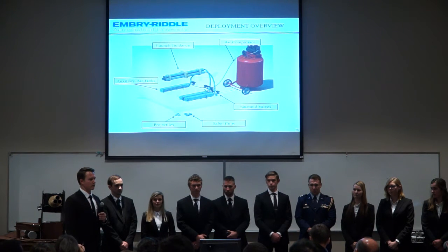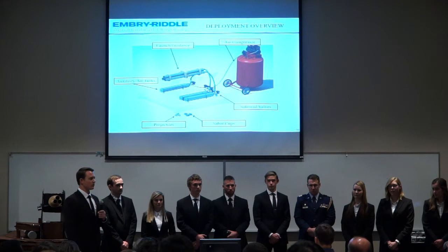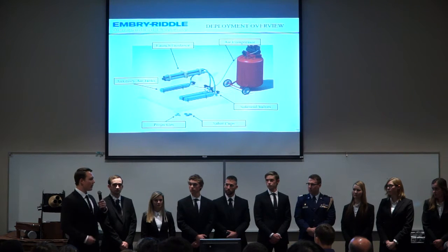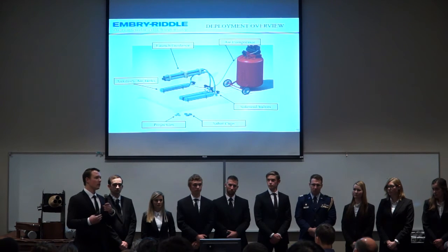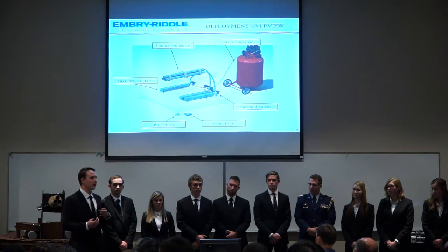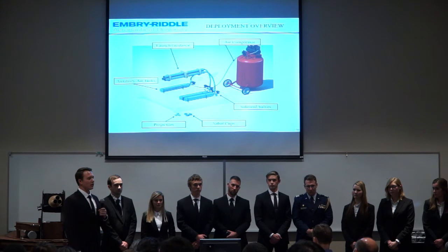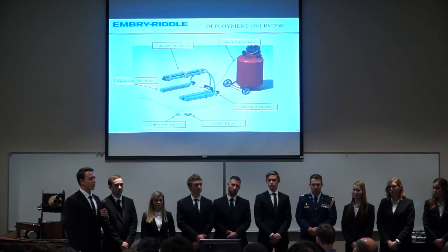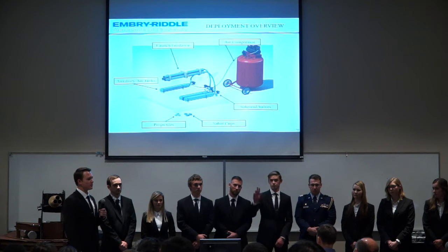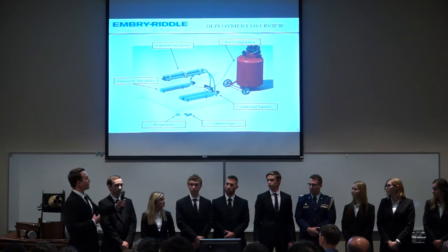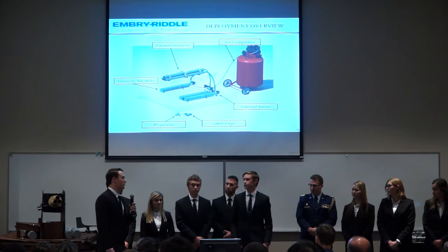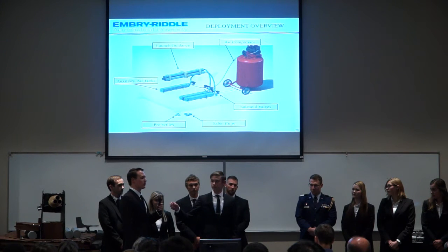So I'm looking at those sabot cups, sorry. Could they possibly turn in the barrel? For how we have it now, they're covered in felt in order to get a snug fit. We haven't thought of that being a possibility, so we'd have to take that into account in the critical phase. Okay, I only ask because they're kind of short, so I was just wondering, what happens if it gets turned and launched? I'll hand you over to Vinny, and he'll be able to discuss the exact dimensions of those sabot cups.